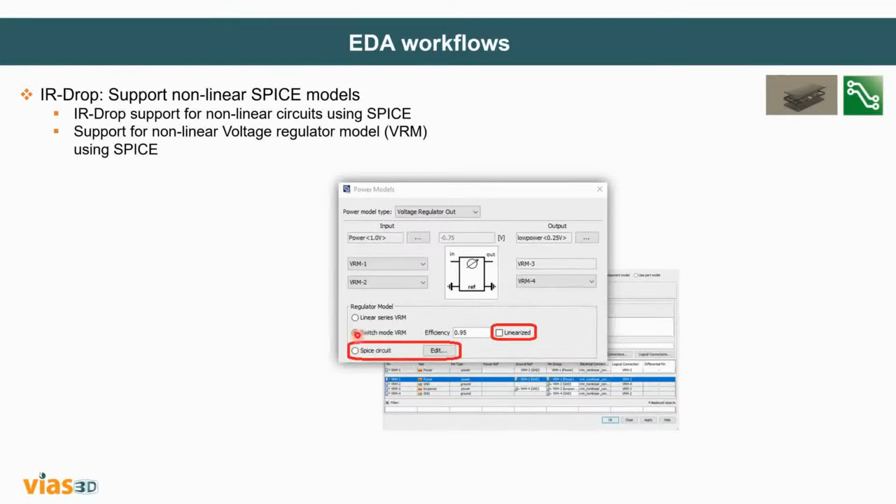So either through a switch mode voltage regulator model, which is non-linearized, or you can import the SPICE circuit directly for IR drop analysis with nonlinear elements.